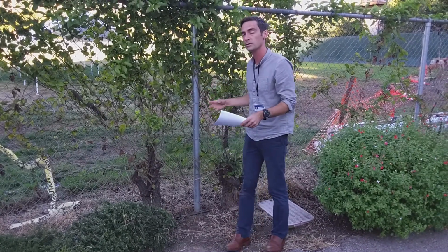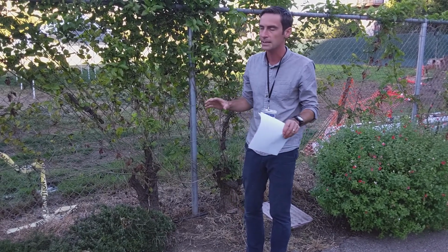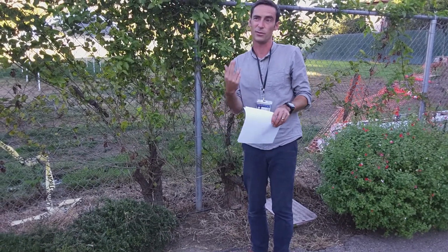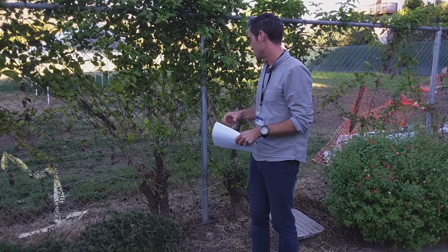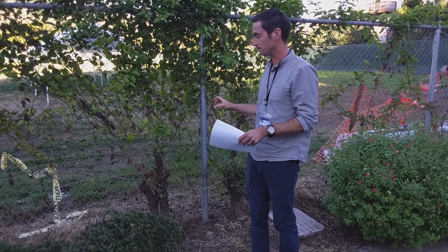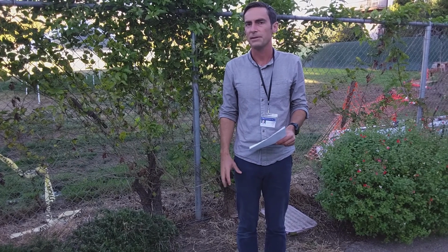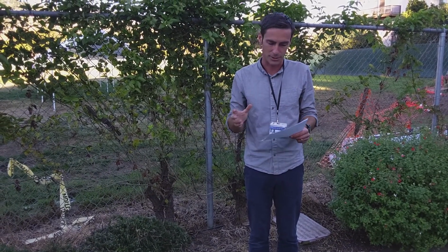This one is the most constrained. This one is all 6 degrees of freedom, locked down, eliminated. So if I were to draw a diagram of that, I would have to show forces in all directions resisting it when some Yahoo is pushing on it and pulling on it like I am right now. Okay, so that is a fully fixed situation between the pole and the ground. And as I say, this is all a little bit complicated. If you keep your eyes on the fact that there are 3 rotational and 3 translational degrees of freedom, there are 6. You can keep track of them every time.